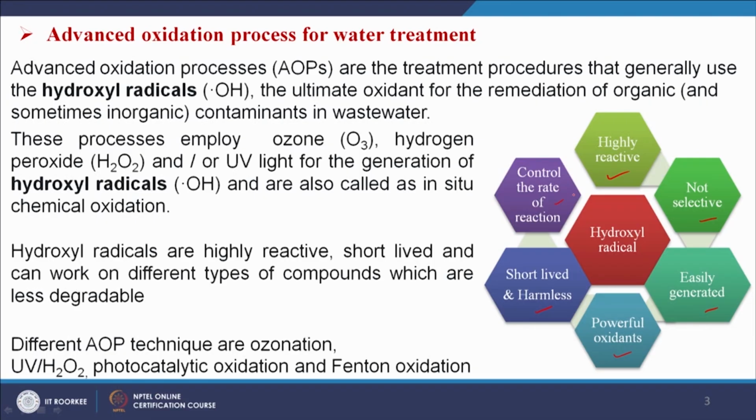So, we will see here advanced oxidation processes are the treatment procedures that generally use hydroxyl radicals, the ultimate oxidant, for the remediation of organic and sometimes inorganic contaminants in wastewater. The process employs ozone, hydrogen peroxide and UV light for the generation of hydroxyl radicals and is also called in situ chemical oxidation.